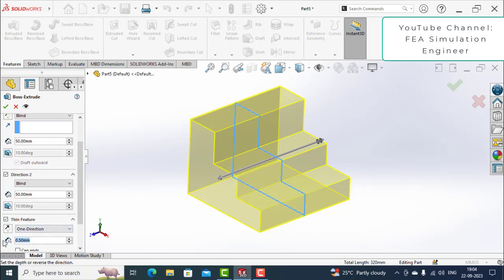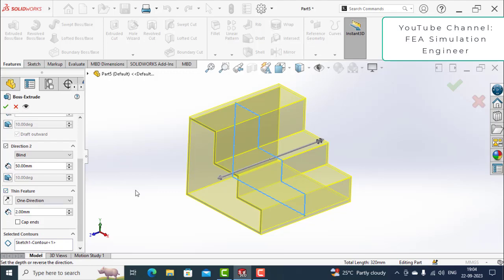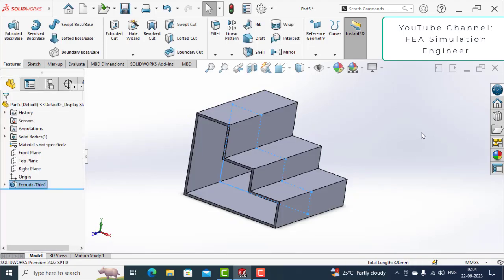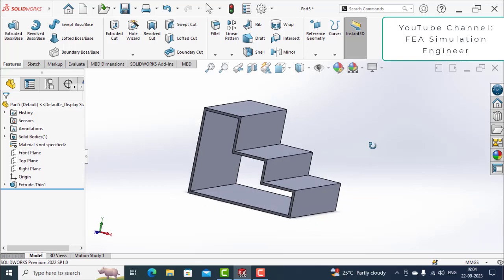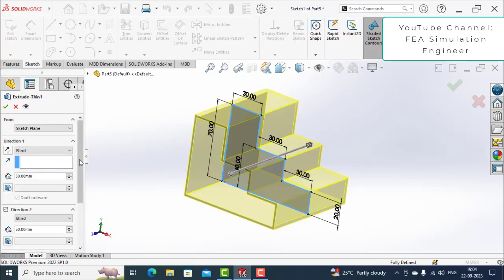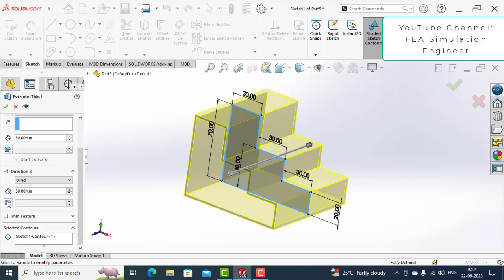Now you can see the difference with the thin feature on, see, it is a hollow feature. Now you can accept the model, otherwise you can again go to the extrude and edit the sketch and switch off the thin feature.